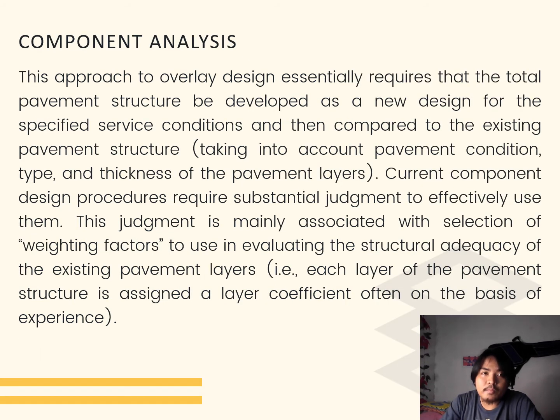Next is component analysis. This approach to overlay design essentially requires that the total pavement structure be developed as a new design for a specific service condition and then compared to the existing pavement structure, taking into account the pavement condition, type, and thickness of pavement layers.